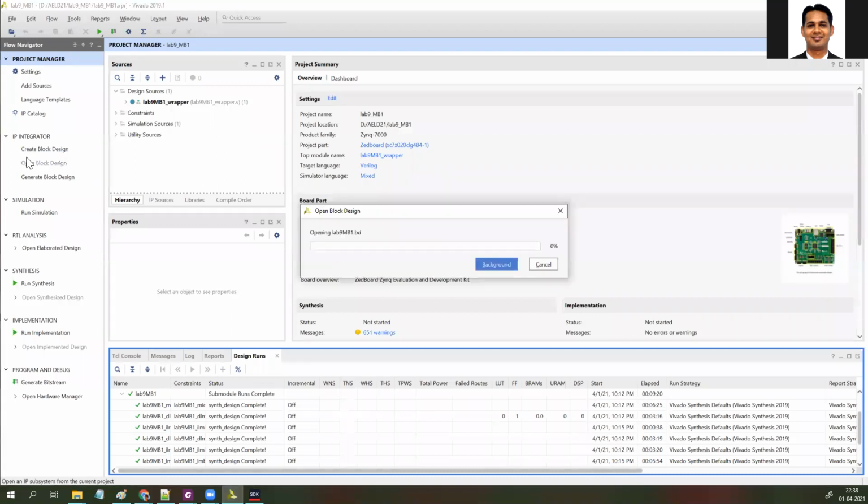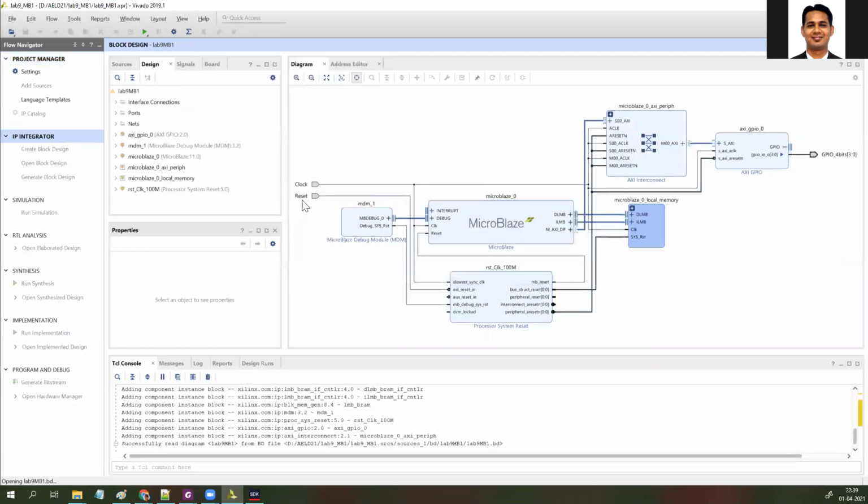first I will go back to our block diagram, and we can see that we need to do 2 things. The first thing is that we need to write a small test bench, and this test bench will make sure that the appropriate reset and clock signals are generated, because we need to drive the clock and reset.